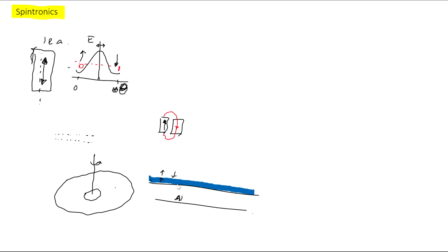And information can be stored in the form of magnetic domains. We discussed that. And domains can be stable. There is a certain area between domains, as you remember, the domain wall. So domain walls are limited to, it depends on the film that you use, but you calculated the domain wall width, and typical widths are, let's say, 10 to 40 nanometers. And it depends on the material, it depends on the thickness of the film, so it can be optimized.